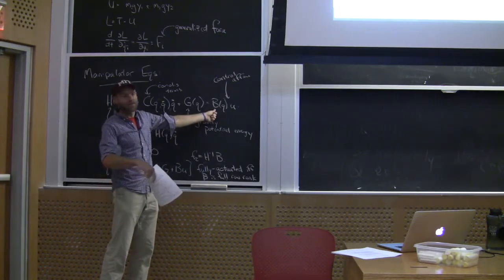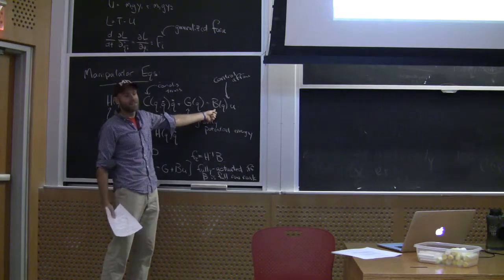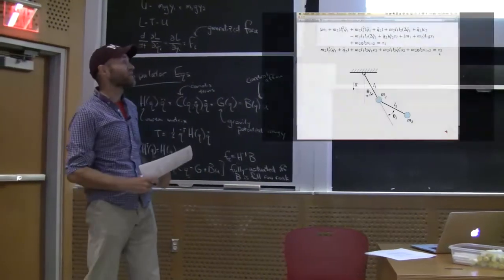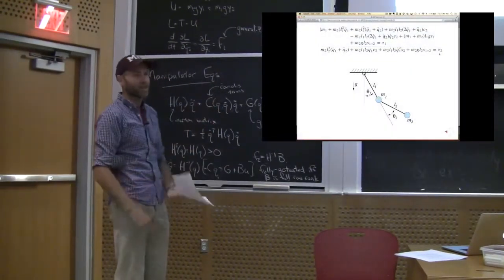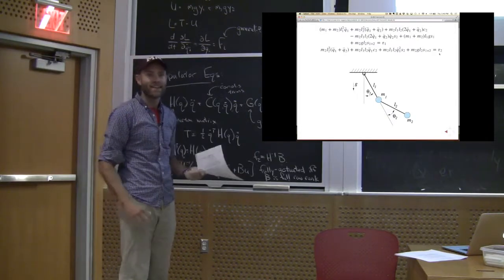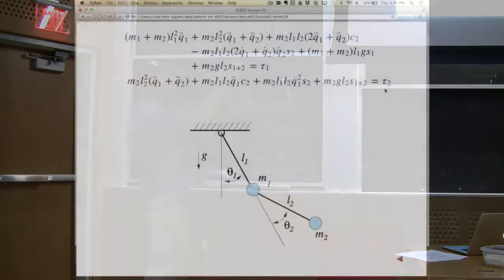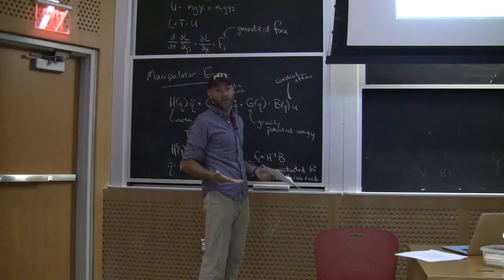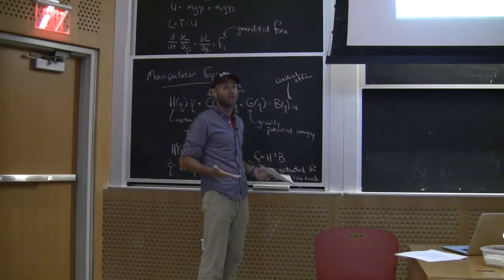So Manolis, who is actually teaching in the class just now, likes to tease me. He says, Russ, if you had more funding, would you work on fully actuated systems? It's not just if you can't afford more actuators. There's actually something fundamental. That seems like a weird thing to do, like, okay, we forgot to put a motor at the shoulder. That's not the point. The point, even though it seems silly, is that the model as drawn, with an actuator at the elbow but not at the shoulder, is effectively the model we're going to use to understand walking. That is one of the simplest models of walking robots.